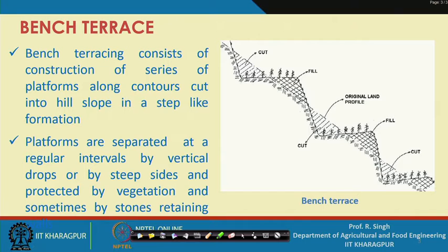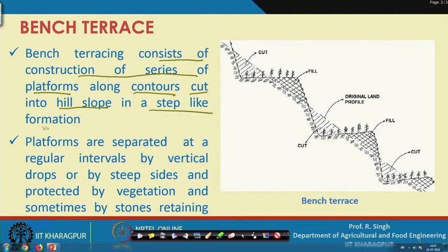Just a recap, bench terracing consists of construction of a series of platforms along contours cut into hill slopes in a step like formation. So, basically a series of platforms, that is what bench terraces are, and they are constructed along contours and primarily meant for hill slopes, that is wherever the land slope is steep and there is a step like formation that is created after cutting the soil.